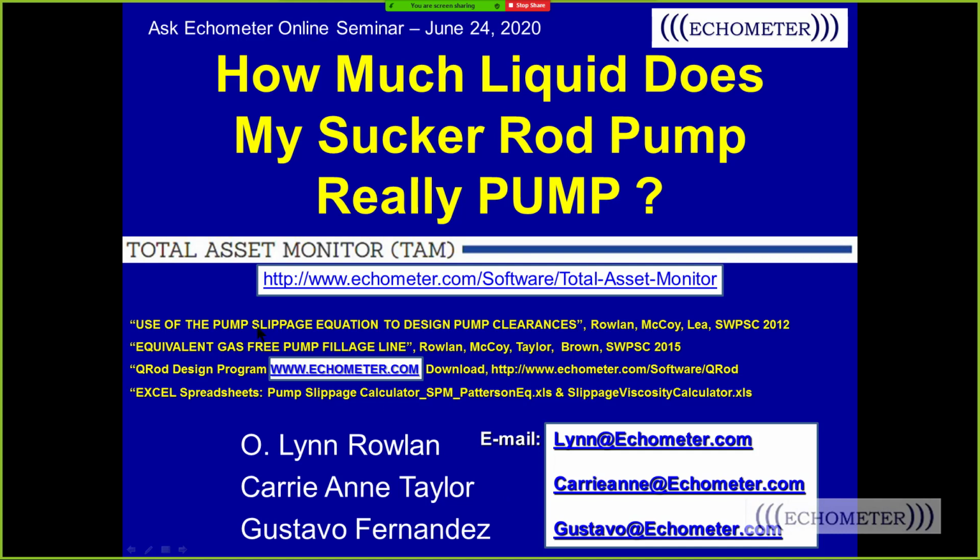There's a couple of references that we have that you'll be able to download. We wrote a paper back in 2012 on the pump slippage equation that was developed at Texas Tech between 2000 and 2007. And then we recently, in 2015, presented a paper on a thing we call the equivalent gas-free pump fillage line. So we draw a line on the pump card showing how much of the pump displacement is gas and how much is actually liquid.